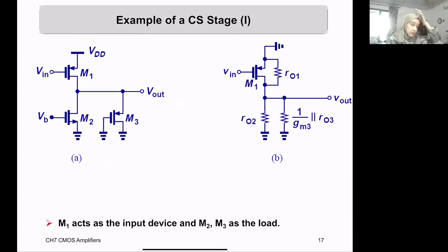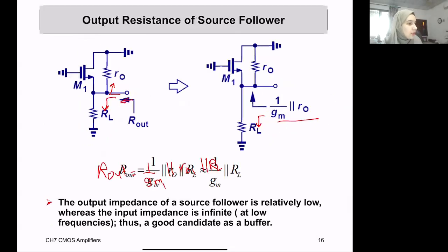Okay, so Ma'am, in the last basic example, how did you calculate R out? Basically, you can do it with the standard way of applying a test source at the output, Vx, having a current Ix, and making the input short. Therefore, you will basically do all that work, but I'm just doing it in a quick way.